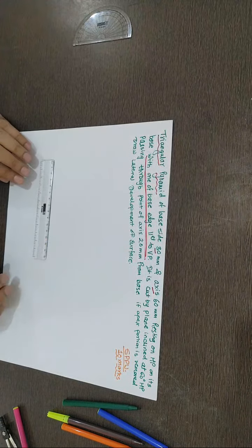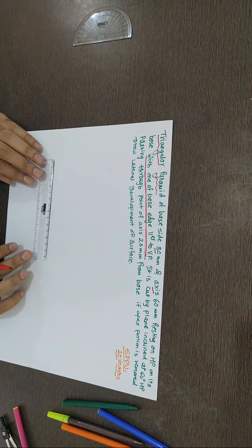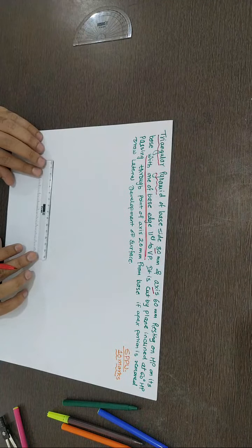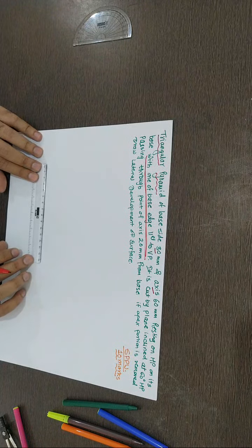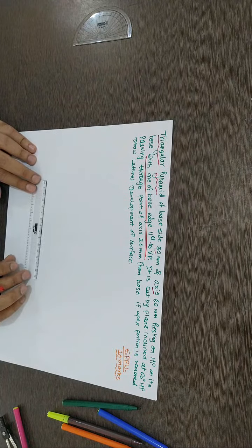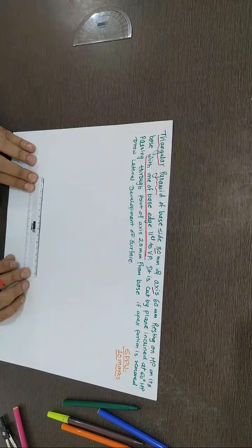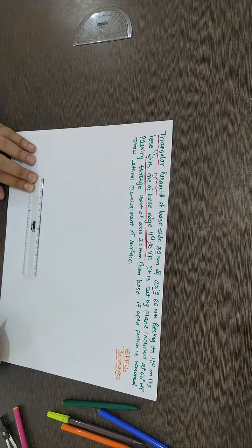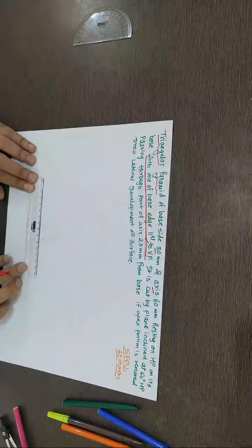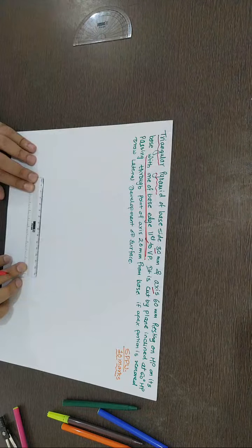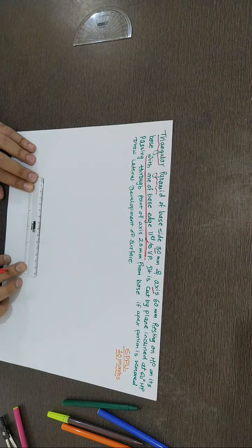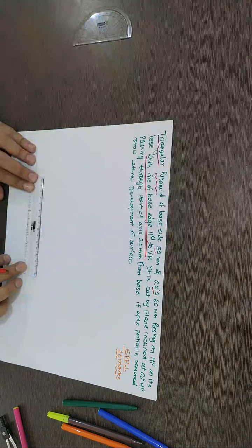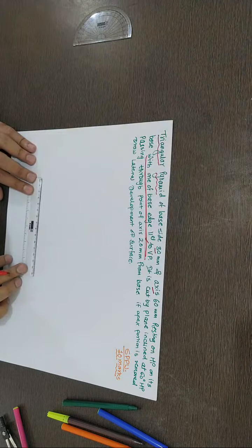So first I'll start with the top view. You can follow the same procedure for drawing it. The dimensions are very small, it's 30 mm, so a very small pyramid actually. So let's draw. What is the condition? One base edge is parallel to VP, as discussed in the similar previous problem. When it is mentioned that a base edge is parallel to VP, or a rectangular face for a prism is parallel to VP, in that case in the top view one of the base edges should be parallel to XY, parallel to the horizontal line. Clear?